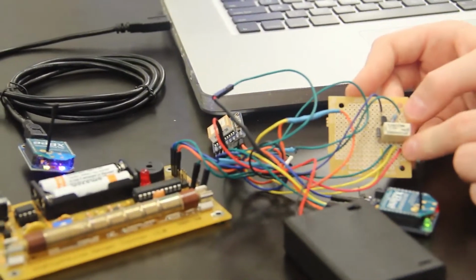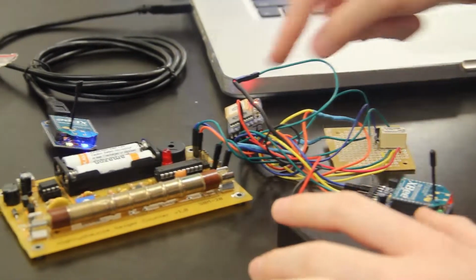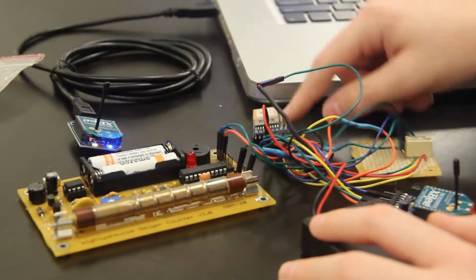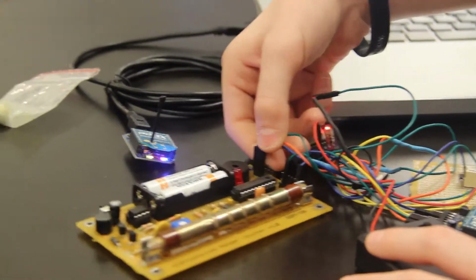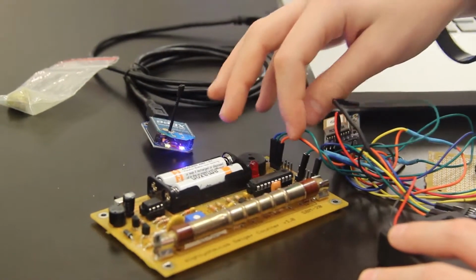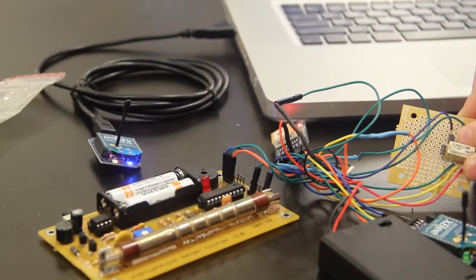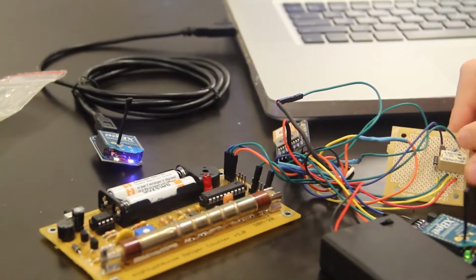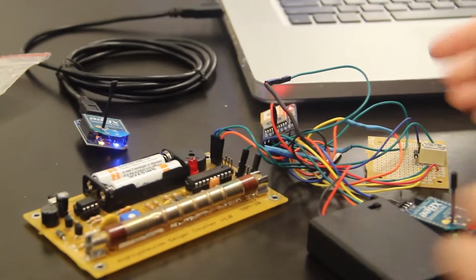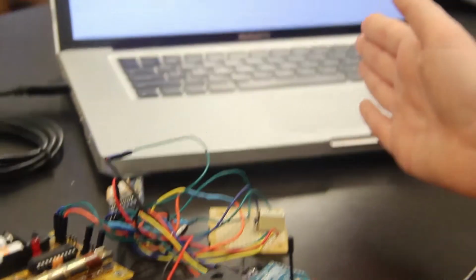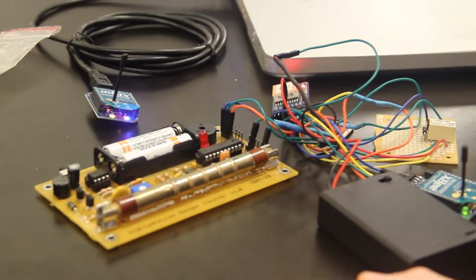which presented itself in this relay here, which switches between transmitting Geiger counter data to the XBee and GPS data to the XBee. It is controlled using this pulse out pin, which I repurposed so that it can control this tiny little chip here, which is just a simple transistor. It decides whether current can flow through or not, and in doing so, whether a little switch inside is flipped one way or the other, allowing either Geiger counter or GPS data to go through.